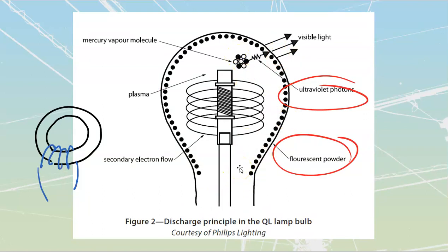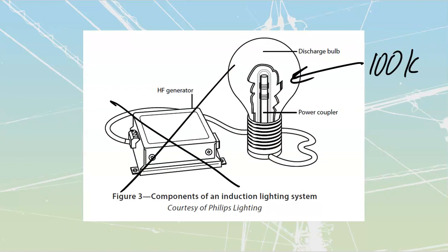Low maintenance requirements, once they are put in place, they usually do operate fairly well for a long period of time. And we do not get much of a change in our light output based upon temperature the way that we do inside of a fluorescent. A fluorescent, when the temperature drops, has a harder time emitting electrons off the cathodes, which means that fluorescent is going to have fewer electrons, which means fewer collisions and fewer light. These ones, we've just got a trapped gas inside, so it's just going to happen the same, more or less, at all times.